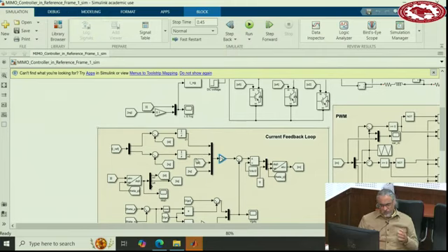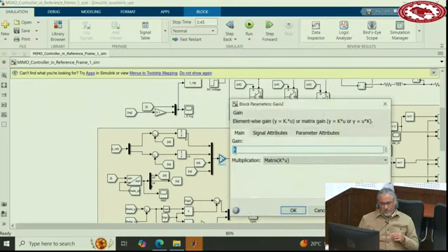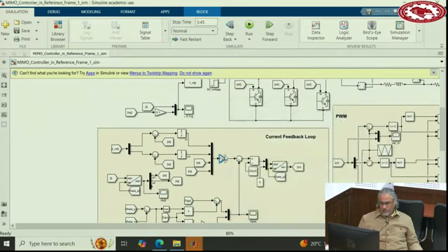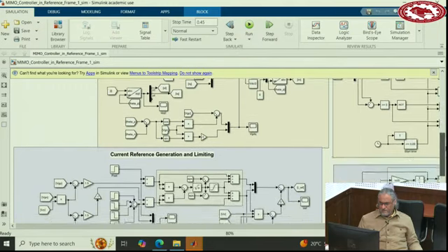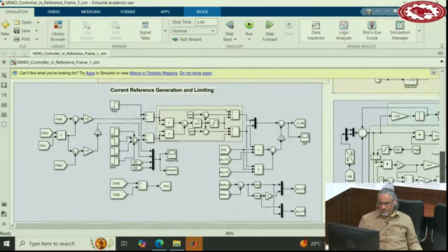So the input to this K, X, is a state variable of the first integrator, a state variable of the second integrator, ID and IQ. So all of them come and multiply into K in a matrix form. So K is a 2 into 4 matrix. And that gives you U. Then here are the feed-forward terms. The other parts are exactly the same.